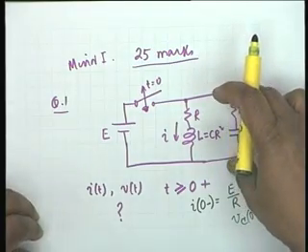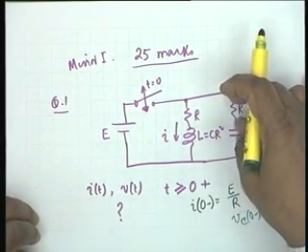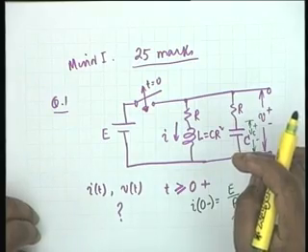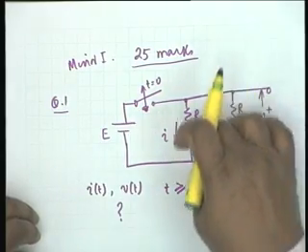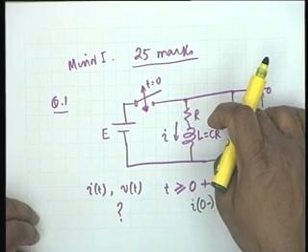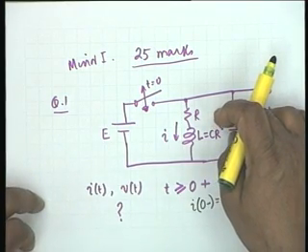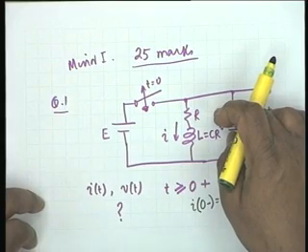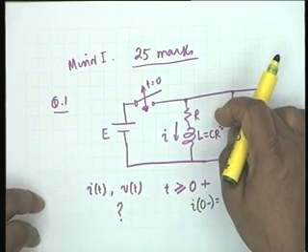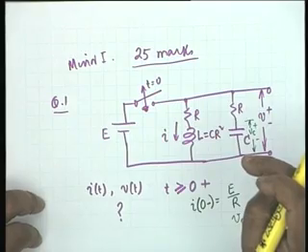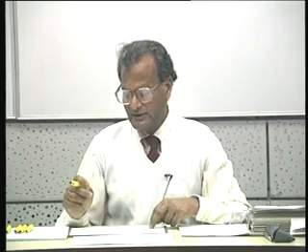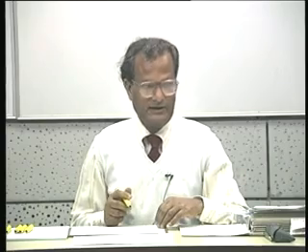This suggests that at t equal to 0 plus it is a single loop circuit. This suggests that you should use Thevenin's equivalent, not Norton's. Some of you have used Norton's and then did not know how to manipulate. The simplest thing would be to use Thevenin's equivalent, as it contains one loop only. Do not make it more complicated than what the circuit given is.